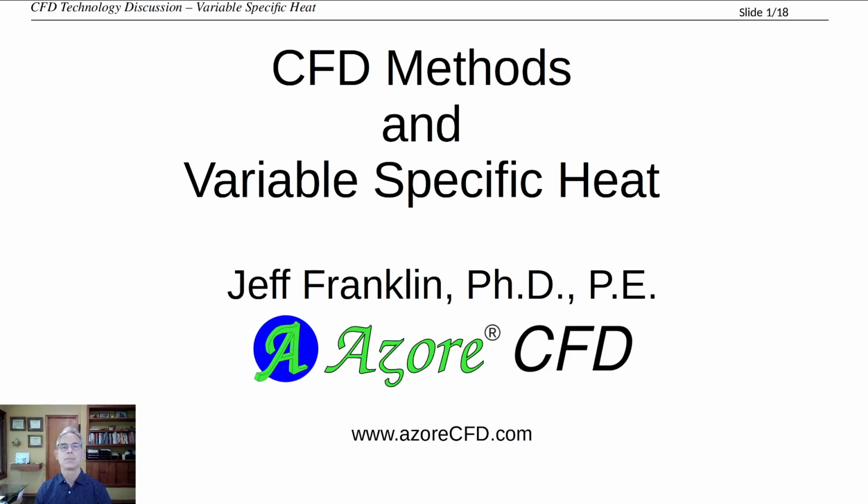The title of this presentation is CFD Methods and Variable Specific Heat. Oftentimes when you run a CFD simulation that includes the energy equation, you would like to account for the fact that your specific heat, or the thermal capacity of the fluid that you're simulating, changes significantly with temperature, or perhaps you have a multi-component system where the thermal capacity of each one of the components is significantly different from one another, and you would like to accommodate and account for that when you solve the energy equation.